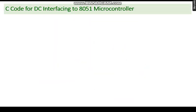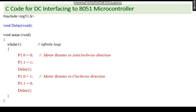Here is the simple code for this. This is the beginning of the program, #include reg51.h. First we make P1.0 equal to 0 and P1.1 equal to 1, which will rotate the motor in the anti-clockwise direction. Then it will rotate in the clockwise direction by changing the supply, and we have to write a delay function for this.